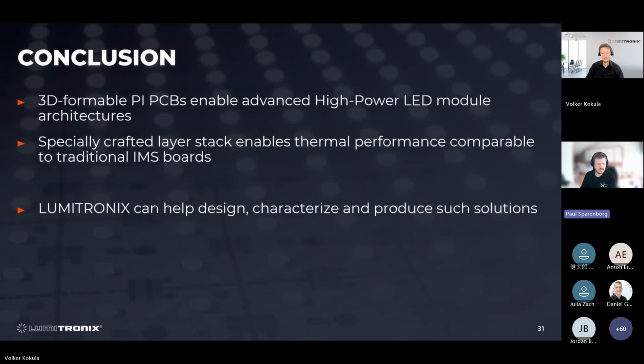We have conducted a lot of experiments with thermally conductive plastics, but honestly speaking, we are not a plastic manufacturer, so we are not doing plastic molding or plastic injection, and we are always cooperating with partners. From our experience with heat conductive plastics, you're able to improve the heat design and even achieve pretty nice designs, but it's not viable for very demanding technology.